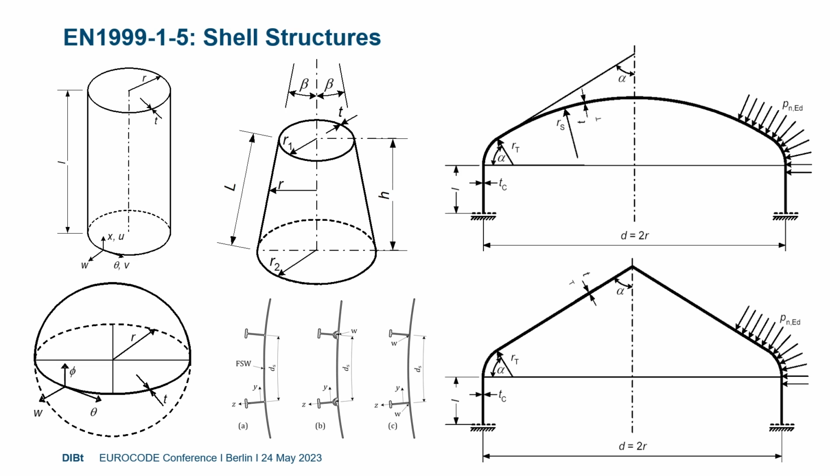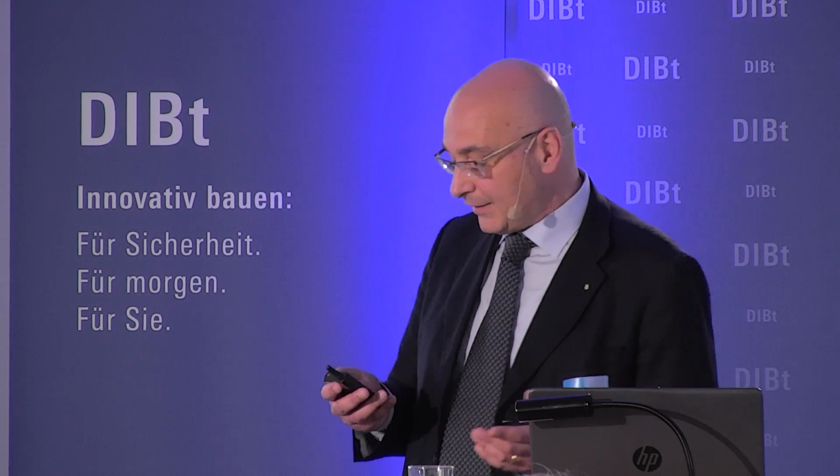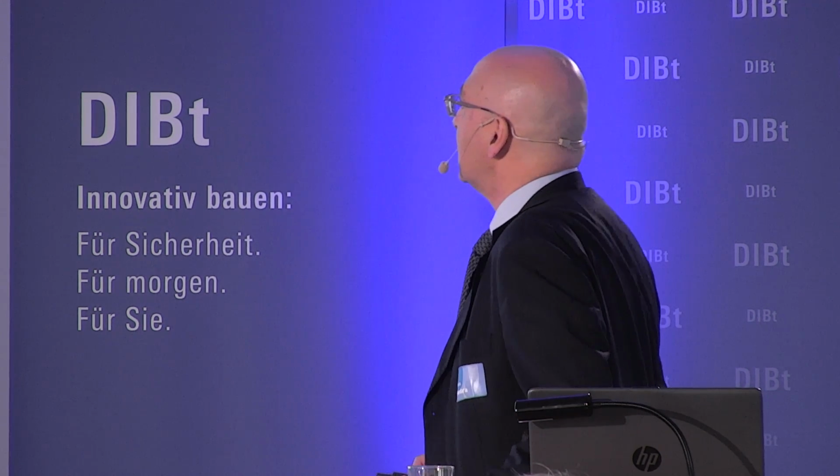It was mostly modeled on the corresponding part 1.6 of EC3, but considering the particular behavior of aluminium alloys, in particular as far as the plastic behavior is concerned, with its consequences on the buckling curves of aluminium.